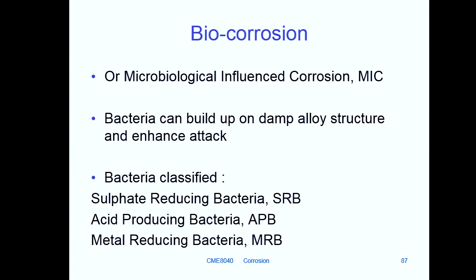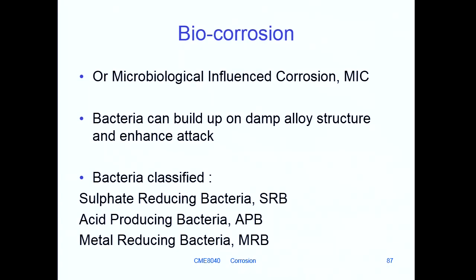And as you might imagine, one of the mechanisms that occurs is that you've got the surface of your steel, you get a film build-up on the top, which is of the bacteria and organic matter, and you then have a possibility of getting oxygen differential. If there are holes in that film, you can get oxygen-rich areas and oxygen-depleted areas, and that will give you enhanced corrosion.